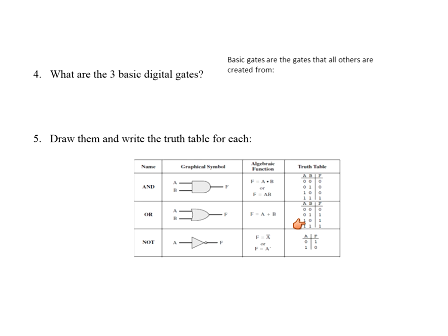So how does the AND and the OR differ? Just in the mixed states, right here. When you have a 0 and a 1 on the input. With an AND gate, you don't get an output, but with an OR gate, you will.